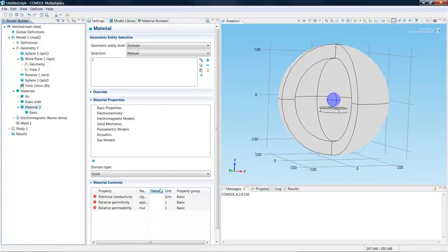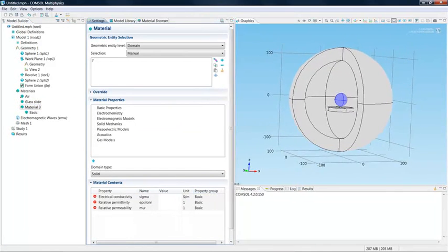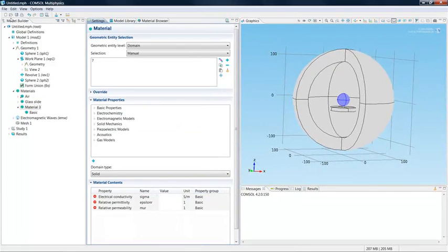So we got it. Now for the properties of this material, we can do it wavelength dependent. So for that, we have to come to global definitions. We realize that we want maybe to shine different wavelengths of lasers, different frequencies. So then you want these properties to depend on the wavelength. Sigma for now is going to be 0, mu is going to be 1. So mu equal 1 means that we're not interested in magnetic effects. They're negligible.